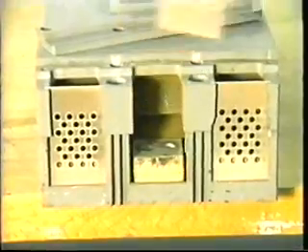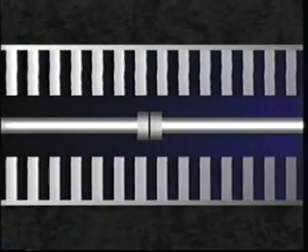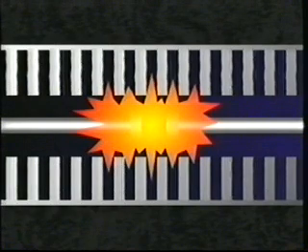Arc extinguishers dissipate the large amount of energy created when high current or short circuit fault is interrupted. Arc extinguishers usually consist of specially shaped steel grids isolated from each other and supported by an insulated housing. When the contacts are opened, the arc drawn induces a magnetic field in the grids, which in turn draws the arc up into the grids. The arc is then split into a series of smaller arcs and extinguished.